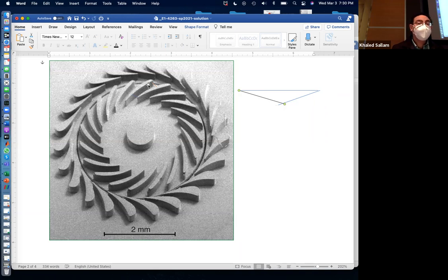And also, what is the other proof that W has to go like this? The direction of the rotor. The rotor expects velocity to come this way. The velocity cannot go to the rotor this way. You cannot enter like this. If this classroom door is a well-designed door, people should approach it normally, not with an angle. They should allow the passage to really guide toward it. So W has to be going like this.